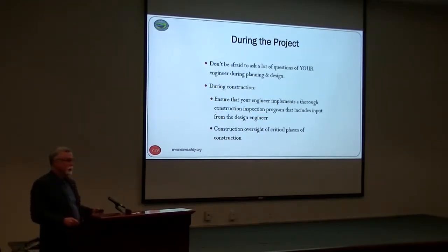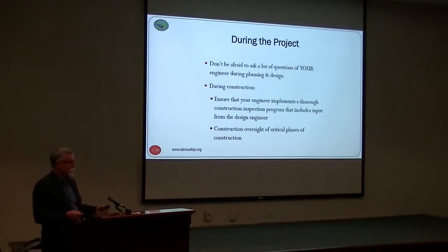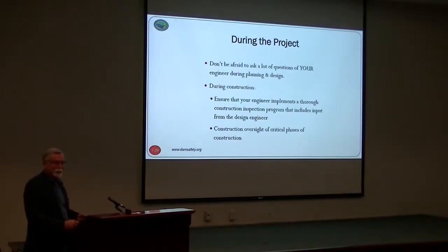During construction, make sure that contractor is building it right. Is he putting in that reinforcing steel? Is he doing the right size steel? And is he putting the right spacing? It's critical. Joe and I can design the best dam, but a contractor doesn't have to build it that way. And once it's built, what's under the dam, what's inside of it, you'll never know. So it's critical, particularly internal drains. We show this sand and gravel. If you contaminate it, say you had a rainstorm and mud washes down inside that gravel, that drain is now completely contaminated, and the contractor's got to dig it out and start over. But if he covers that up before the inspector looks and says, hey, I built it just like it shows, your drain will never operate properly.